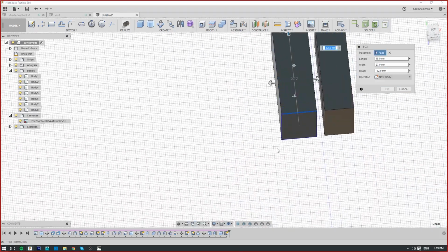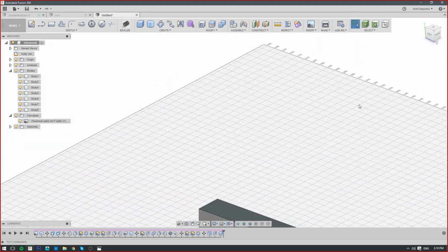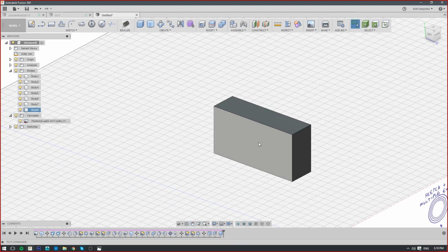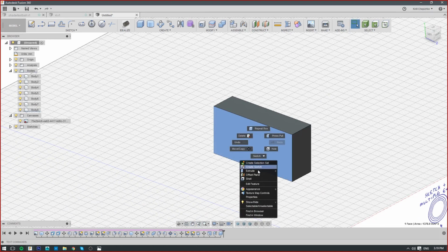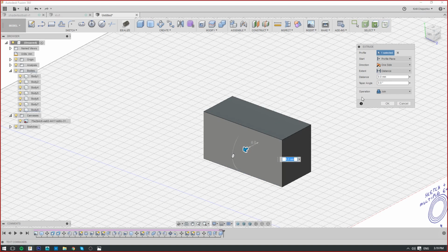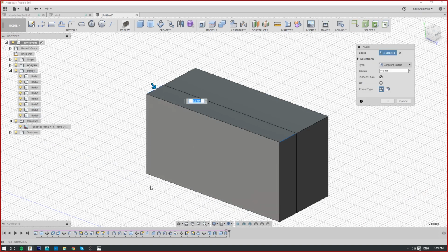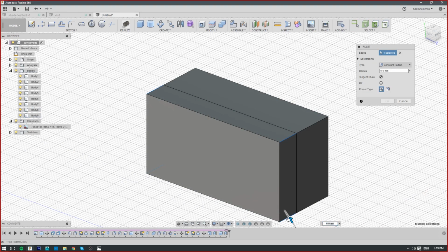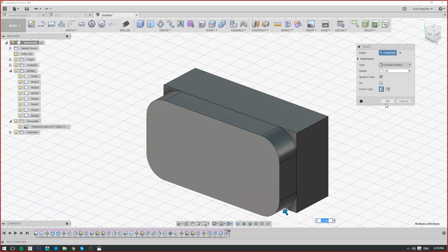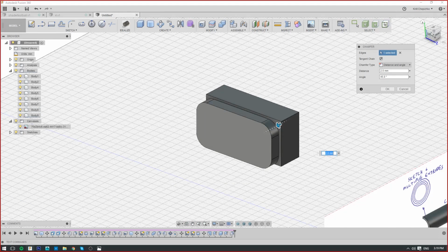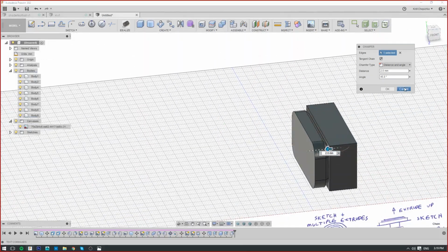Which I'll have to spend some time matching. But if I wanted to actually match it, I will just take this face and extrude it and make it a new body, and this will be a much better match. Yeah. Even though our final result, for example, is not exactly a box, it's just a good way to match things together like that. Just work from existing faces.